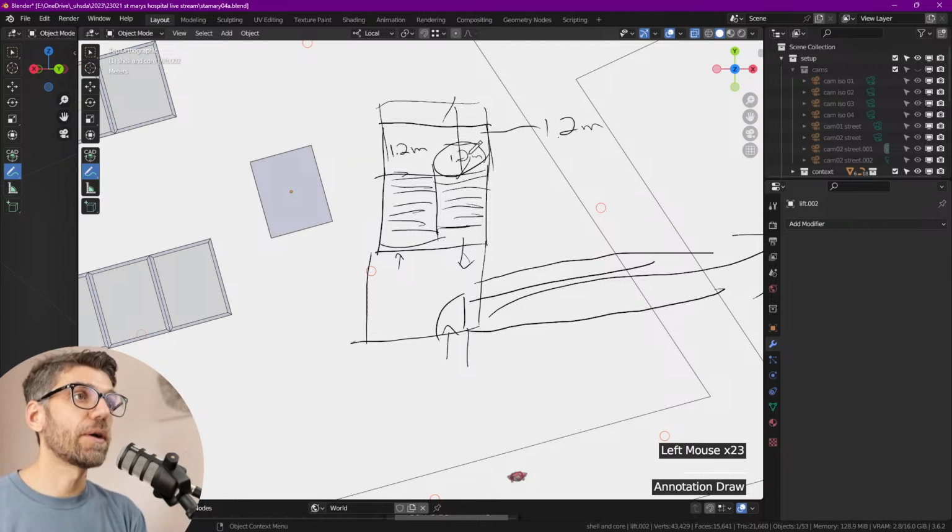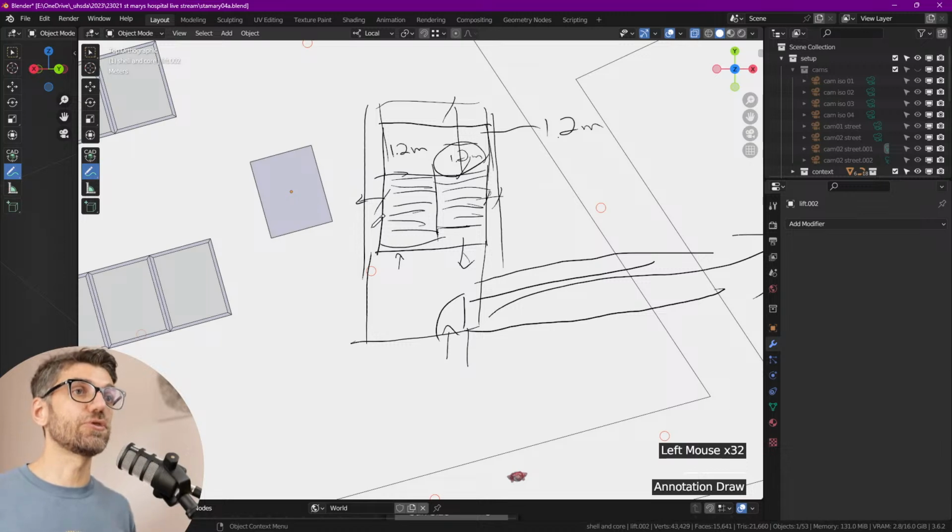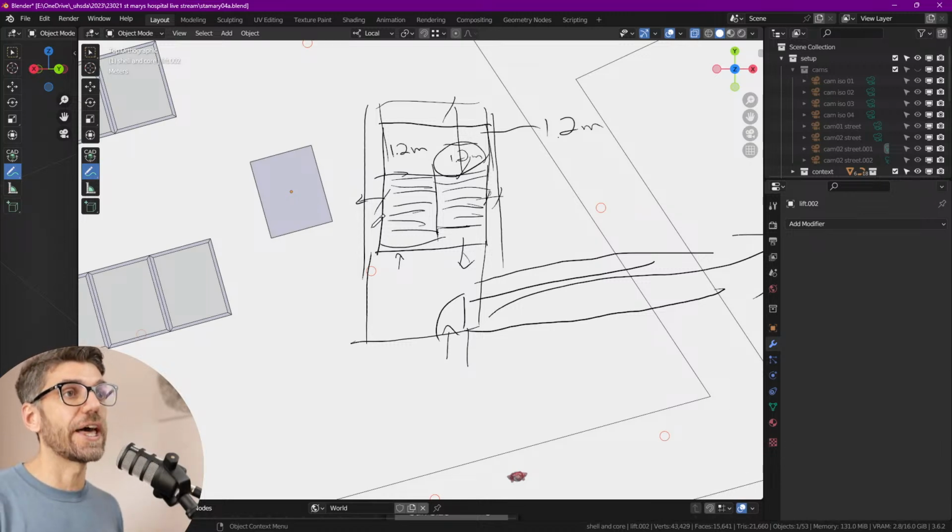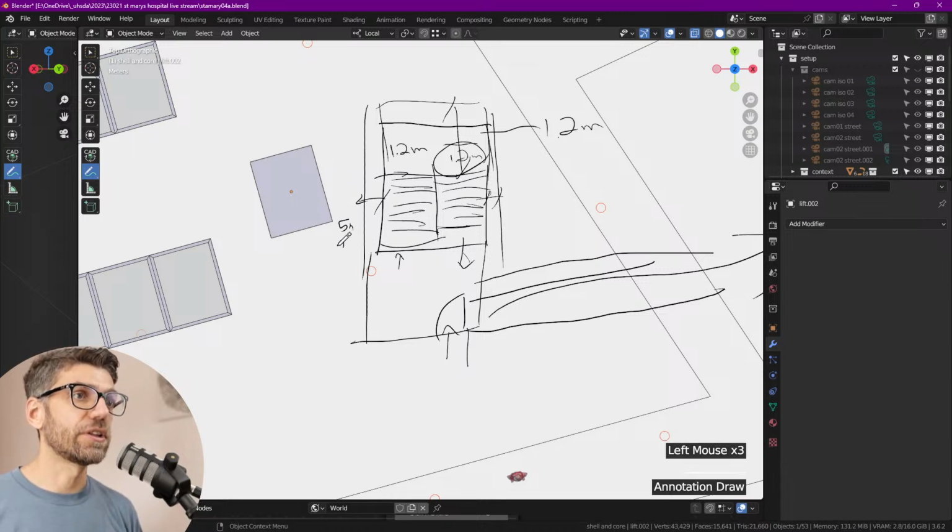So what do we have here? 1.2, 1.2, so that's 2.4. Then we have walls on either side, which can go a bit deeper here because that is part of the core. These walls are usually used for two things: one is for structure, and two, to stabilize the overall structure for lateral stability. So that should be at least, we can be very conservative here, let's say 500 mil. That's a lot. Let's say 300 mil.